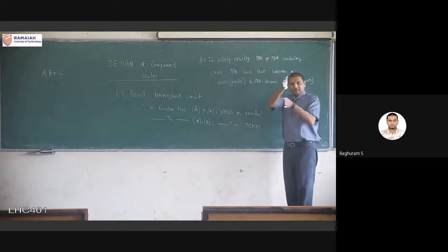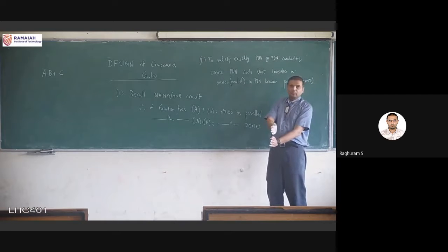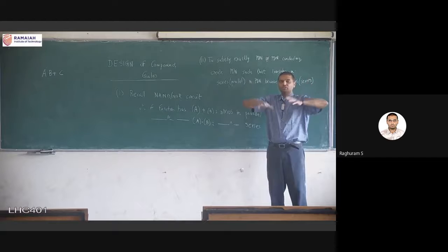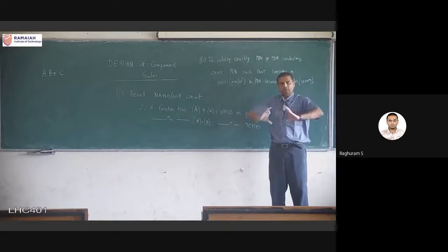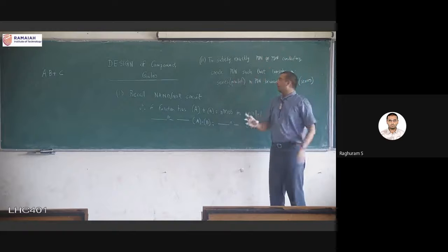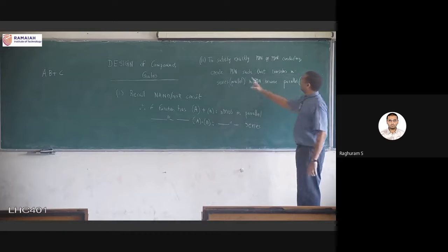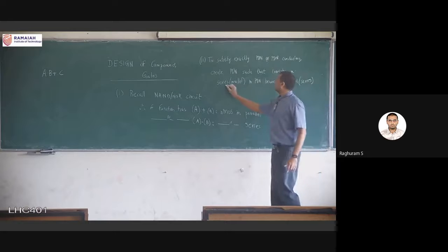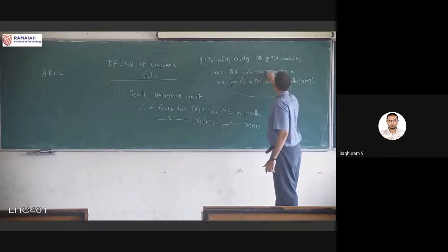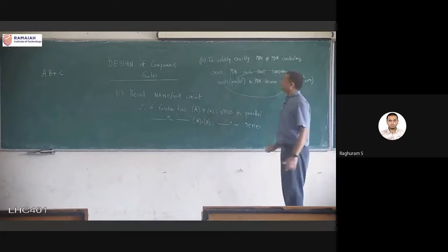Any transistors already in series in the pull down network, A and B in series, you make them A and B in parallel in the pull up network. So just keep following these rules, convert the full pull down network into a full pull up network. Any transistors in series will become parallel. Any transistors in parallel will become series.